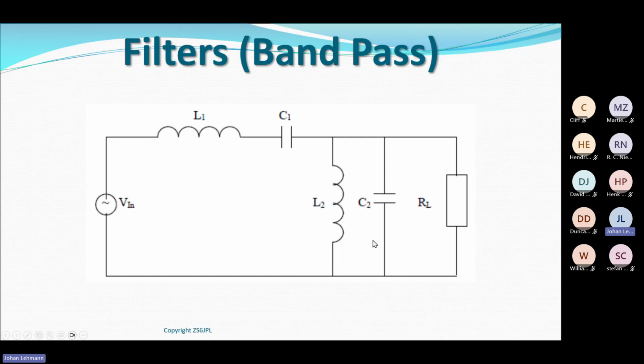And these two together, if it is a low frequency, the coil, the inductor, is going to short it out to ground. If I'm above my passband frequency, the capacitor is going to be a low reactance or low impedance, and that will short it out to ground. Okay, so before my passband, this guy does the work, and on the other side of the passband, the higher frequencies, this one does the work.